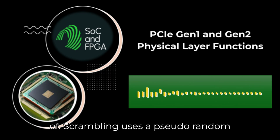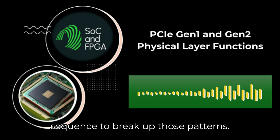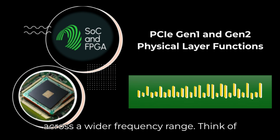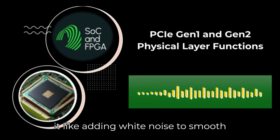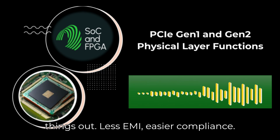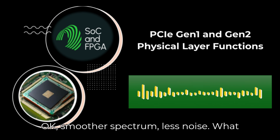Sort of. Scrambling uses a pseudo-random sequence to break up those patterns, spreading the signal energy more evenly across a wider frequency range. Think of it like adding white noise to smooth things out. Less EMI, easier compliance. Okay, smoother spectrum, less noise. What else?